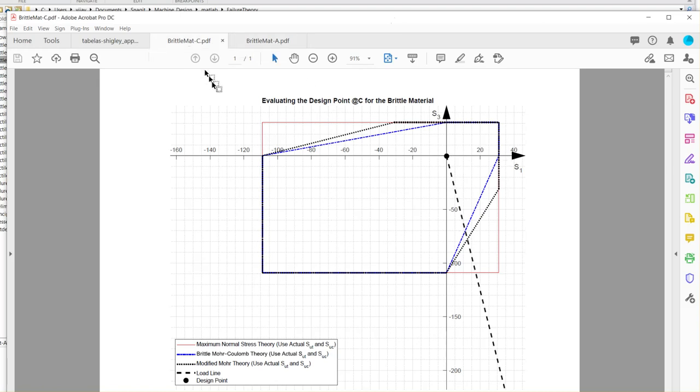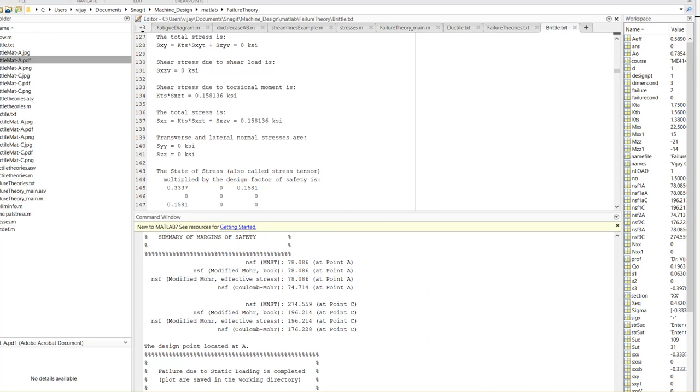You have to watch out very carefully because many times, although we may think point A or point C is the most critical one, sometimes we have to actually plot and see what the failure mode looks like to decide. In this particular case, look at the load values.